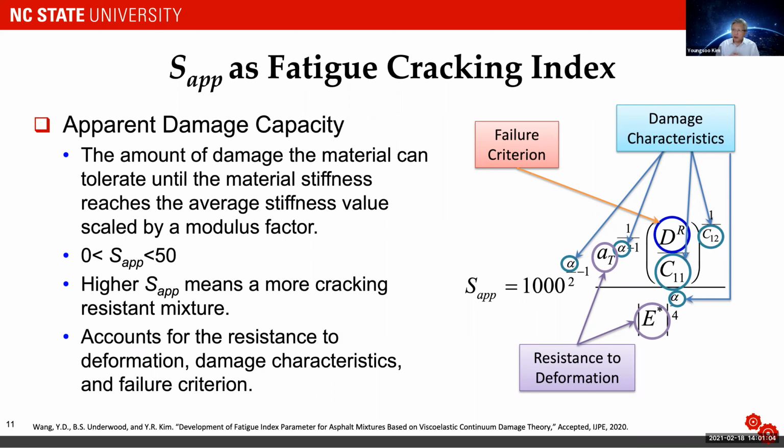I didn't show you the FlexPAVE prediction results, but we published that in TRB, I believe, last year. We had multiple field projects, and we got the original materials from those projects. So we ran AMPT, we ran through FlexMat, FlexPAVE, and showed the comparison between predicted and measured for cracking and rutting. And actually, they look really good. We need to do more of that, but at least some of the existing data seem to indicate that the program is doing pretty well.